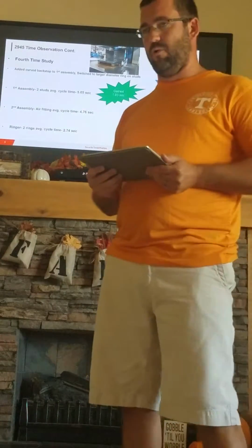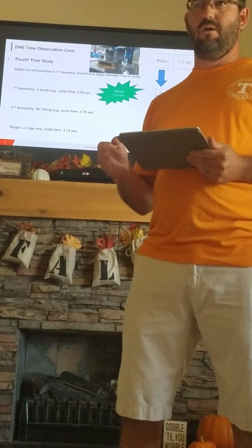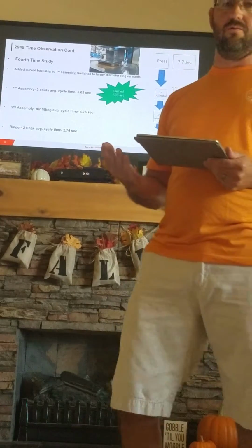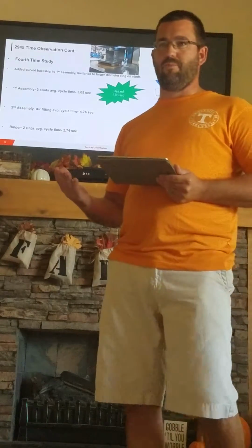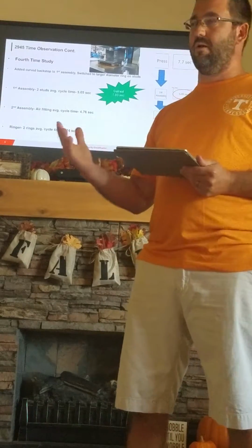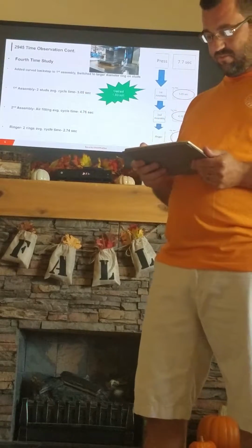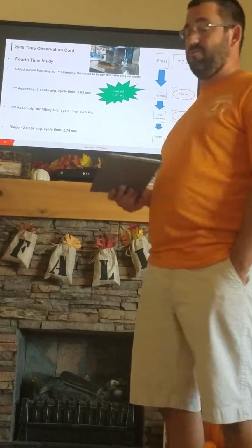So the previous ring that we had, the inner diameter was a little tight for the fit, which would make the application a little tougher. So we went to a larger diameter ring, made the application a lot easier. This showed in their cycle times, which were down from nearly 7 seconds to slightly under 3 seconds now.